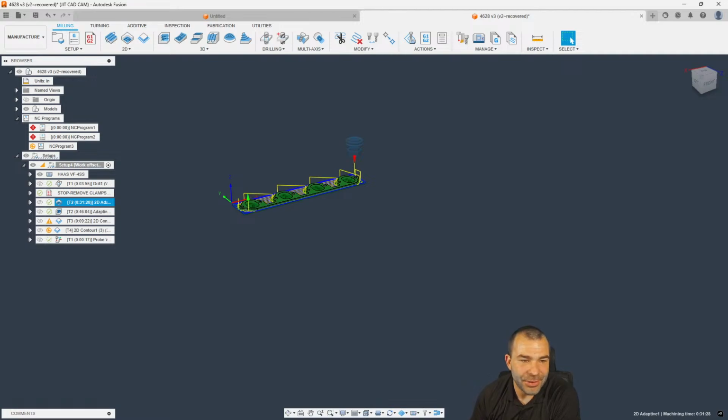So, Deep Thinker's question is, is it possible to add information in for safe tool locations for certain operations? So we have added that in quite a bit for people. We actually just put in a checkbox and we call it a large tool maneuver. With a large tool, it will move, say, your table out of the way, bring it all the way up above machine home, and then over and then back down to your actual tool change location. After your tool change, if it's a large tool, then it would also retract back up.